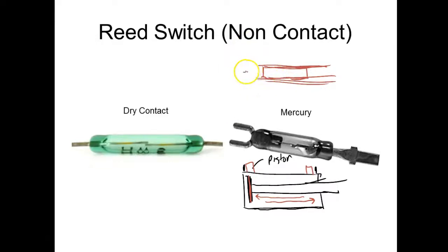And what you do is you slide, and if you looked at the little slot, it would have a little old tiny hook up here. And you slide the little old tiny reed switch in there, and then it's got a little old tiny set screw on one side. Once you get it where you want it, you tighten that little set screw that goes out to the bottom and latches itself into the position you want. That's what we got back here, I believe, is an eighth of an inch.